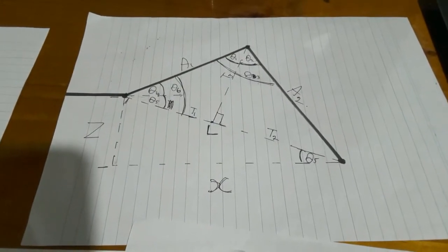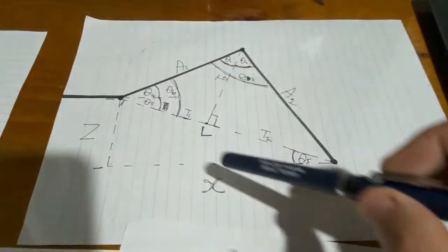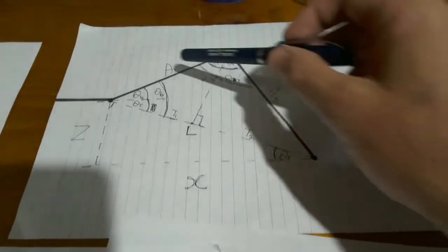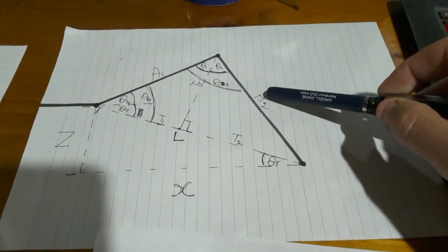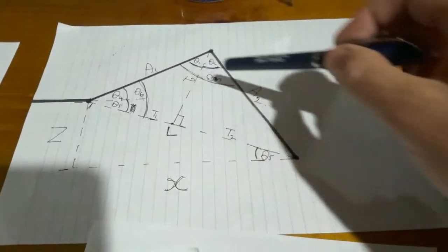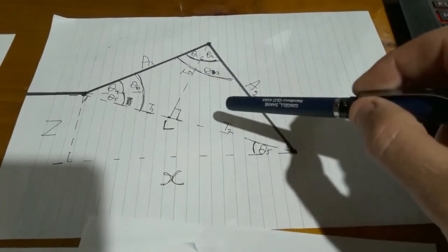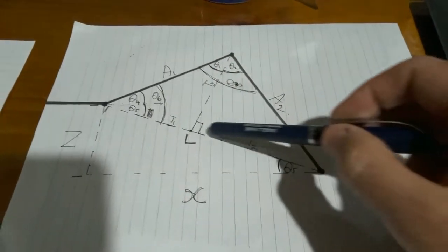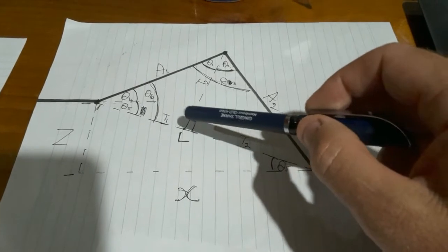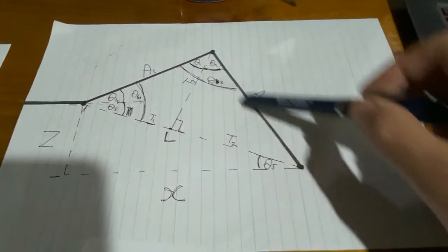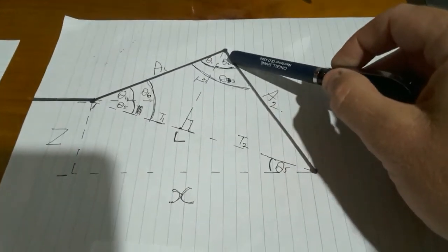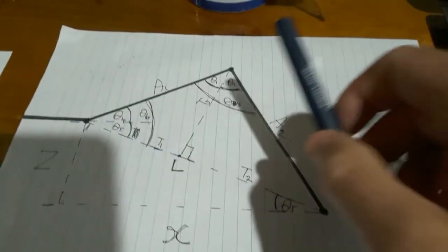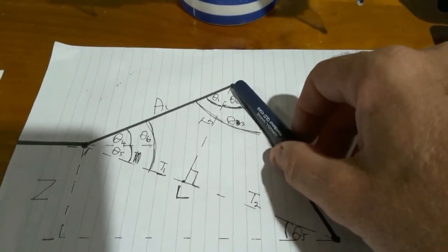Okay, this math error is going to happen anytime I make Z and X so big that L becomes longer than the length of the two arms together. Alright, so anytime that A2 plus A1 is smaller than L, I'm going to get that error. So what I need to do is calculate L. Once I've calculated L, check that L is smaller than A1 plus A2 before calculating the rest. Now if it's not, what we're going to do is make the leg totally straight.